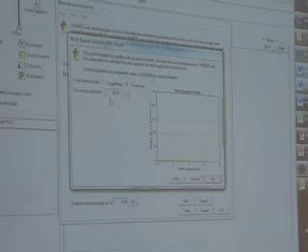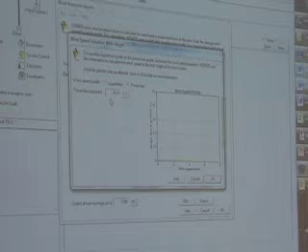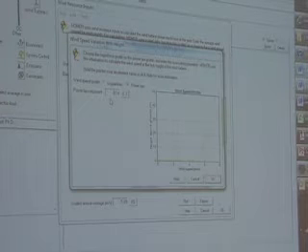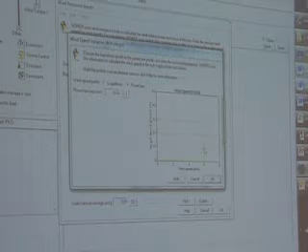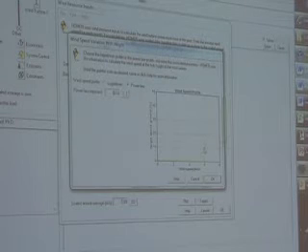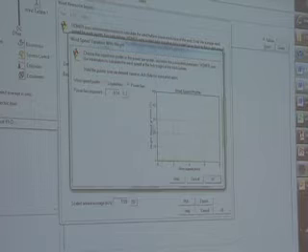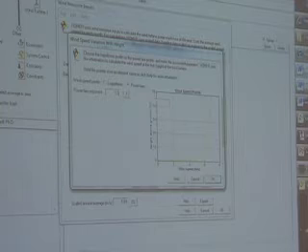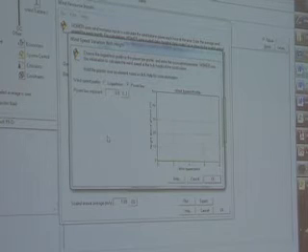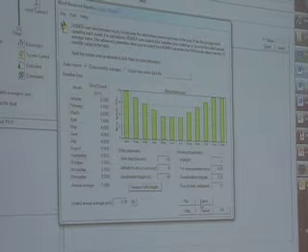Actually, wind shear is a pretty fluky concept. It's not really nearly so smooth a function. But you can see here where we say it's 6 meters per second at 10 meters above ground. As you go to higher heights above ground, it shows how that changes the assumption. And just to show you, you make the parameter smaller and I just reduced the shear. So that's the shear.